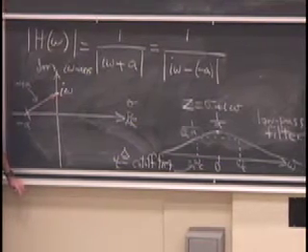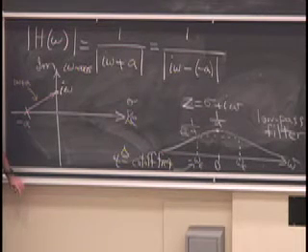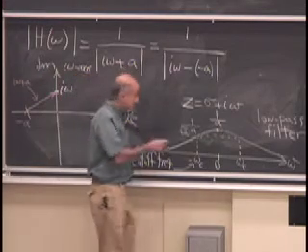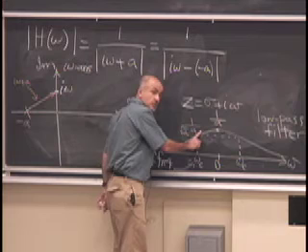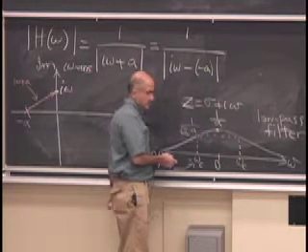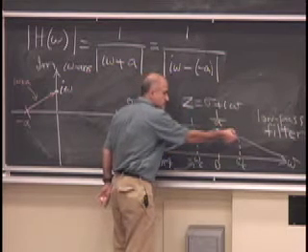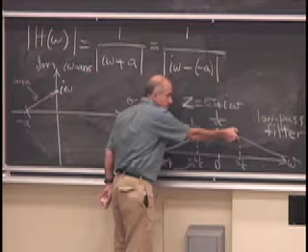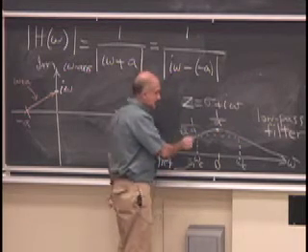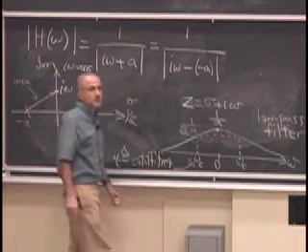Yeah, I did address that point. There is no objective reason for that. It's a heuristic. For practical purposes, in some applications even this is not tolerable; in some applications, more than this is tolerable. It all depends on the specifications of your application. But by and large, in a lot of applications, you can tolerate this much degradation, a 3 dB degradation in your magnitude response, and still consider all these frequencies as having been passed through roughly on an equal footing.